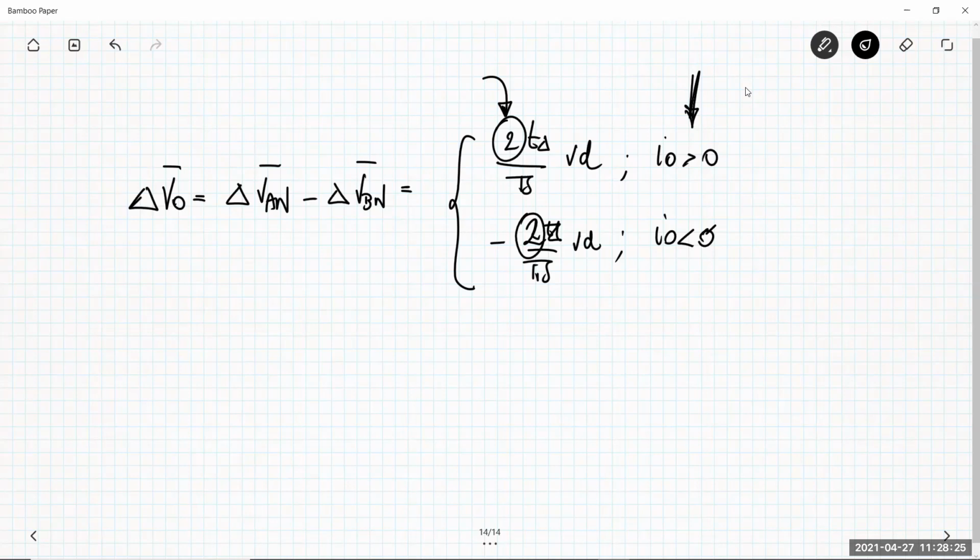So in a situation in which you require very high quality of the output voltage, and you want an effective filter action at the output, then the unipolar pulse width modulator can help to have a better filter action.